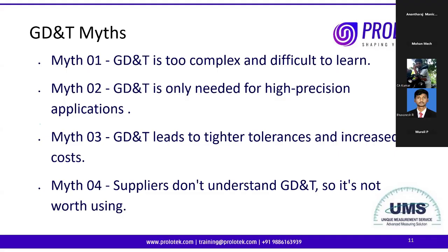So 2018 focuses on how to give GD&T symbols on a 2D drawing as well as 3D models so that it is compatible with the latest CNC machines and measuring equipment. These are one or two major things. There are other changes which are minor. So two important changes are the focus on model-based definition and two symbols being deleted.